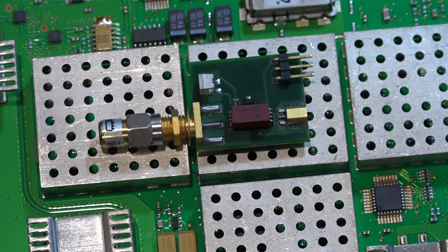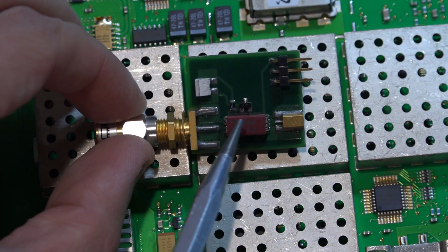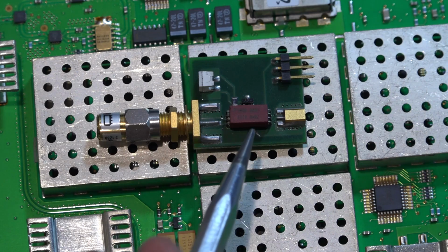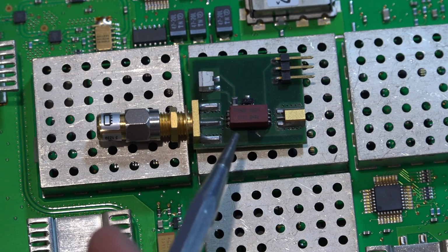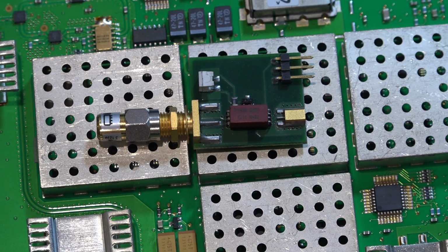So if there is an overload condition detected, it will simply switch this relay. There's a little transistor and a resistor there for the LED. So this itself is most likely not the cause of the problem, because there's really nothing here. Unless somehow the energizing voltage of the relay is leaking into the RF port back into the module, I don't see why this would be the problem. I can test this separately nonetheless just to make sure.